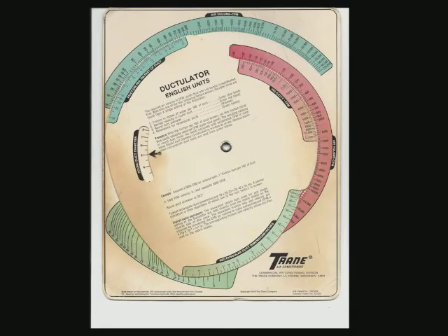So I go to my handy dandy ductilator, and you can see in this picture that it's pretty beat up. This thing's been around for a long time, and I can safely say I use it every day. But if we look on the right hand side for the air volume, CFM, we're looking for 300. Now we want the velocity, the feet per minute, to be between 2,000 and 2,500. Dialing this thing in, that shows us we need 5-inch diameter hose. Or I'm sorry, not hose, but ductwork.